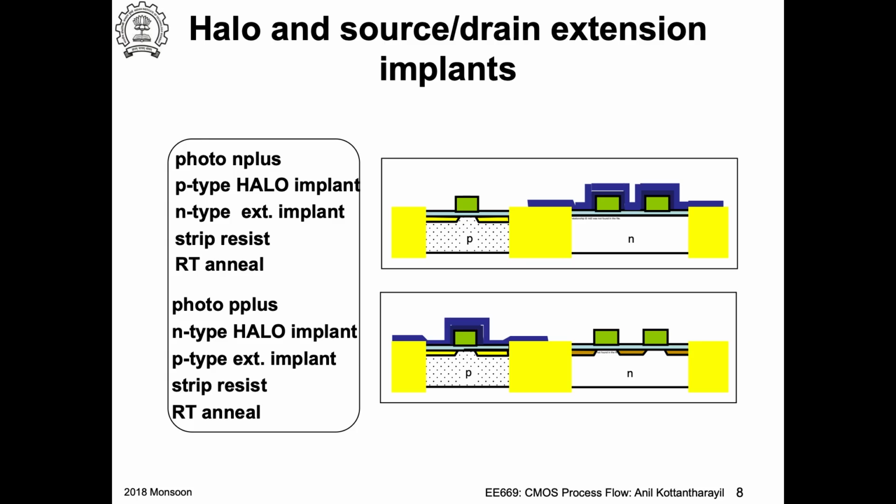But now, suppose I postpone this anneal till the end, where I have already also implanted boron for the source drain extension of the P-channel transistors.